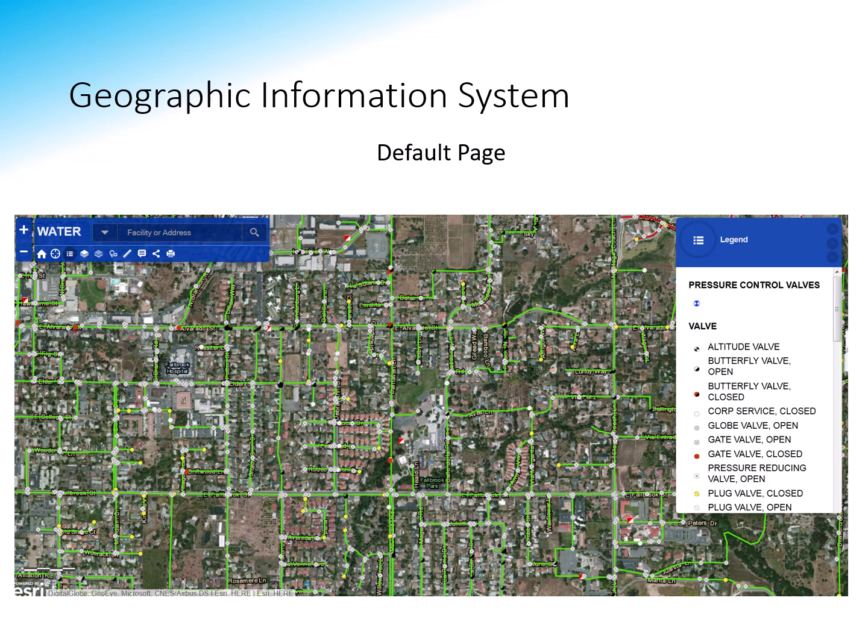Here's I think a really nice example of a GIS system. Just a little side question as you're looking at all of these water mains on here: is this a grid pattern? Is this an arterial loop? Is this a tree system where there's a ton of dead end mains? Anyway, just a little side question, but it looks like honestly it has a little bit of each. It's got a legend over here to identify what is what on this map. That's a nice little GIS map here. And then you can zoom in on it and get even more information.